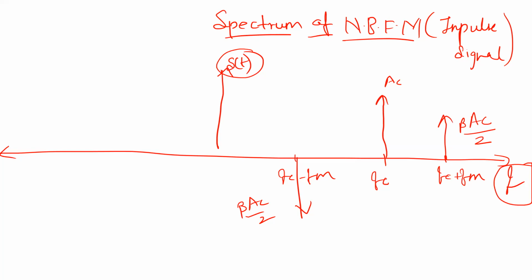But remember, Jerry, always when we draw a spectrum, whatever the mathematical expression, we are going to divide the whole expression by 2. So this will become this. Why? Because it's peak to peak, is it? In this case, we don't want peak to peak. We just want peak values divided by two. Right, okay.